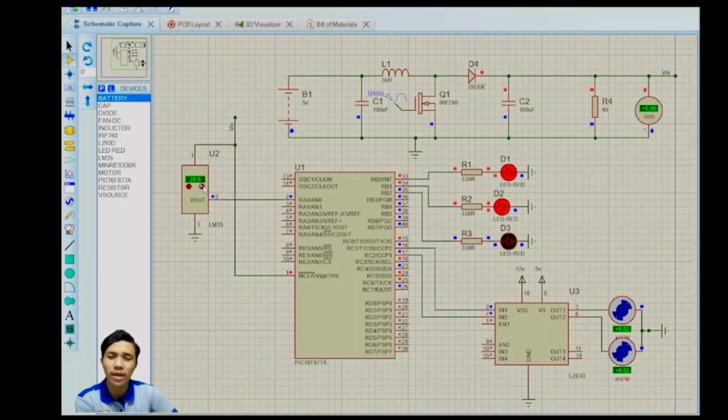and we put it at 28. So now at 28 Celsius, there are 2 LEDs turned on, which are DC1 and DC0, and the motor seems to gain more power and rotation from the PWM duty cycle. And we're going to test the last condition, which is more than 30, and we're going to put 35.